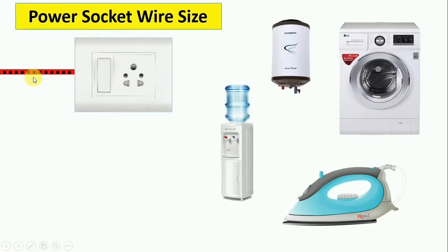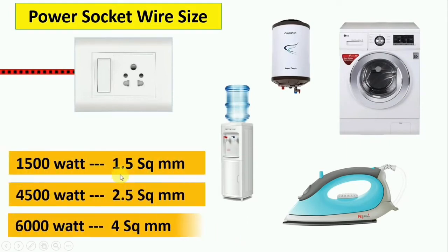When you're talking about power circuits for your irons, heaters, dispensers, and even your laundry sets, it's advisable to use a very good copper cable that would withstand the test of time, as these things are powered on day by day. You find that the wattage consumption of some irons may be around 1500 watts or 4000 watts, depending on the design. So you use these variations. Wiring size for home appliances.